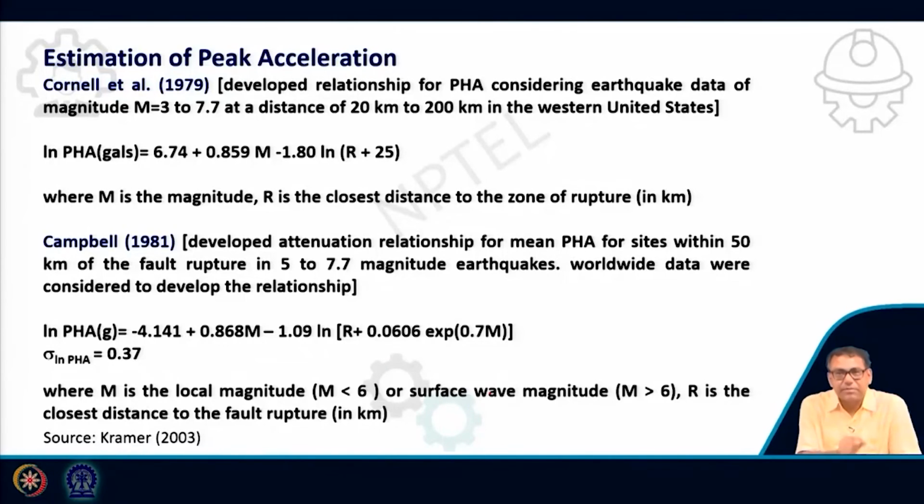And which magnitude is it? It is a magnitude, though it is not mentioned which type. When magnitude is mentioned without a type, generally we consider it to be moment magnitude. Otherwise, the type of magnitude used will be specifically mentioned. If it is not mentioned, then we will consider it moment magnitude, because that is the magnitude widely accepted and more popular for engineering design.